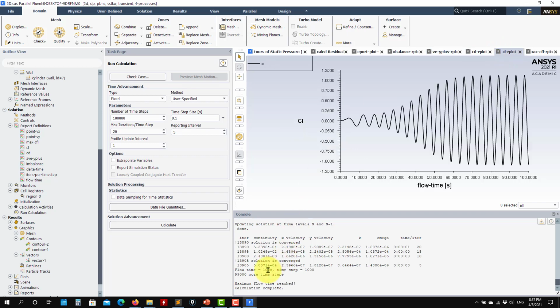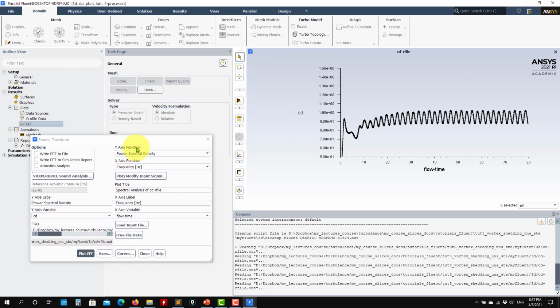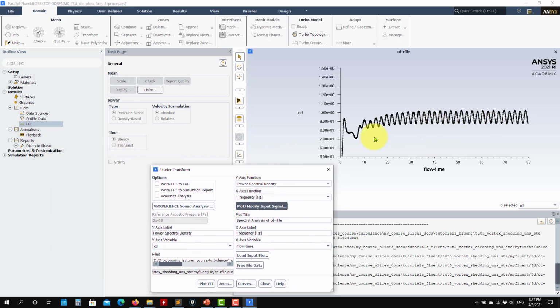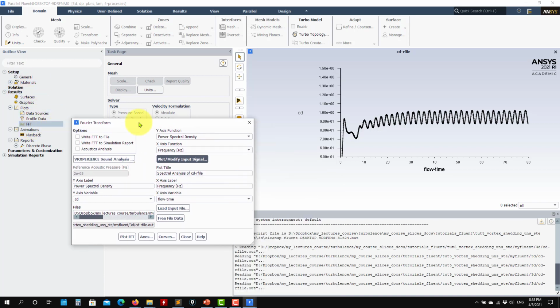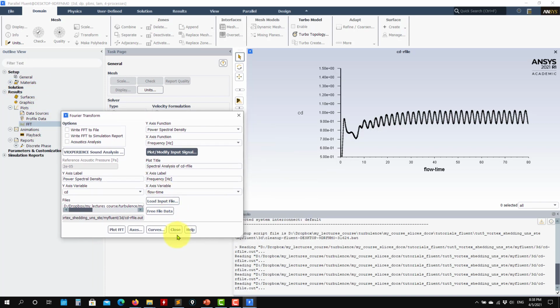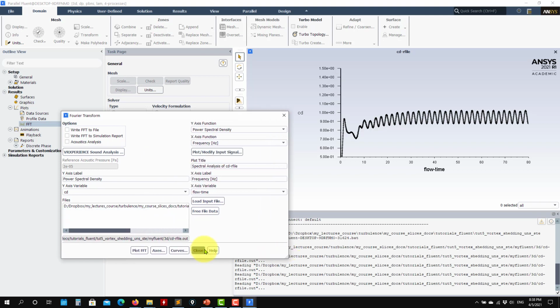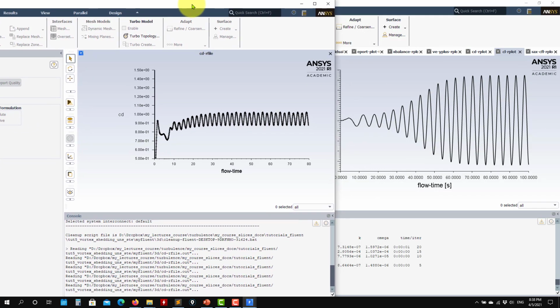Okay, so here I already opened another Fluent session. First, just to show you that to do the post-processing, the signal post-processing, you need to load a case. So see that I haven't loaded a case. I just opened the file directly here. You can use any file in the given format, either the Fluent format, or you can also have a free file format, just the columns.